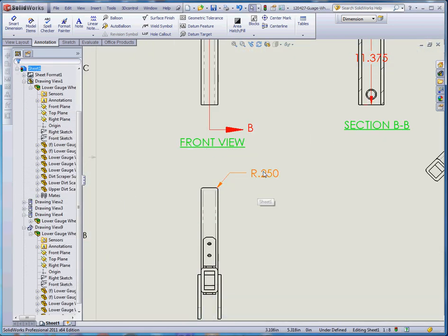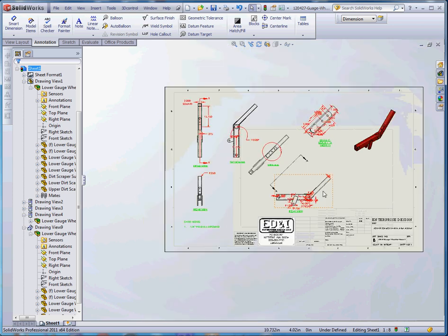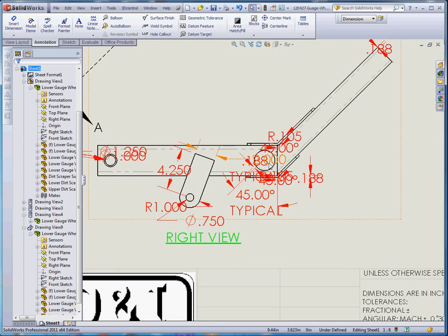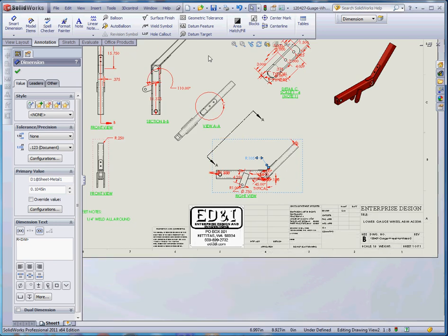So here's a radius dimension. This is going to be the last thing you do for this film. Remember our leader line that we have for that dog leg leader? We want to change that, and that should be about 2 millimeters, or about 8/100ths of an inch in size. Because when you get a really tight drawing like this, and you have a lot of these leader lines, it's nice having it a lot shorter. Typically they are shorter, so let's go ahead and change that.